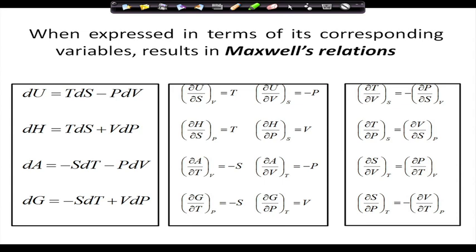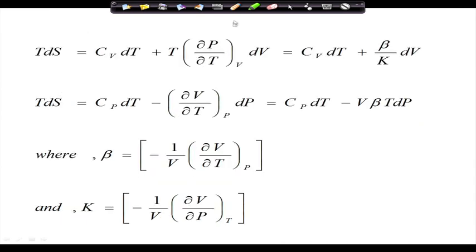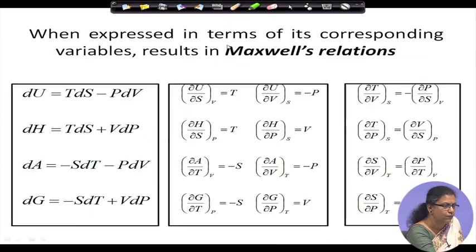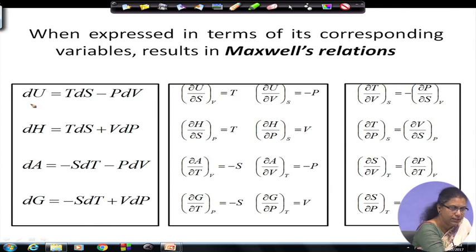Well, the most important property of the thermodynamic potentials with which we will be primarily interested is this. If you observe each and every one of these equations, we find this was the combined first and second law that we have already discussed. From here we have come here. Just substituting A equals U minus Ts, we get this equation. Substituting G equals H minus Ts, we get this equation. So, for each thermodynamic potential, we have got one set of differential equations, number 1.